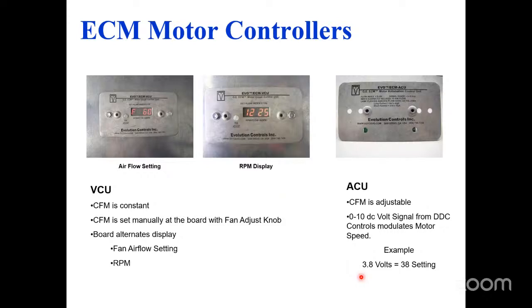All right. There are controllers for these fans. Most of these are ECM at this point. You can still find old school ones that are not. But there's some kind of controller on there. Typically, it is adjusted with a little dial on here. You turn that dial to provide more or less airflow. This is typically adjusted by the air balancer on the project, assuming you, in fact, hired an air balancer.